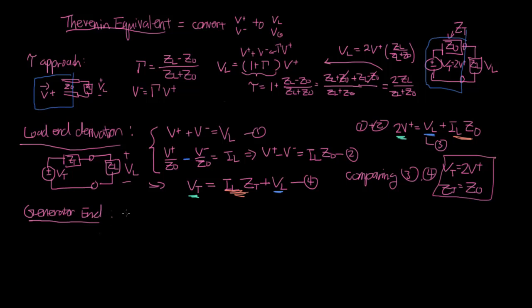the main difference compared to what we had before is that when you were trying to connect a V plus to a VL, now we're trying to connect a negative going wave to Vn, so the incoming end of a transmission line. So remember our transmission line going here, the voltage drop at the output we were calling VL, the voltage drop at the input we're calling Vn, right? So you have a V minus going that way, you have a V plus going that way. Before we were connecting V plus to V load, now we're trying to connect V minus to Vn.